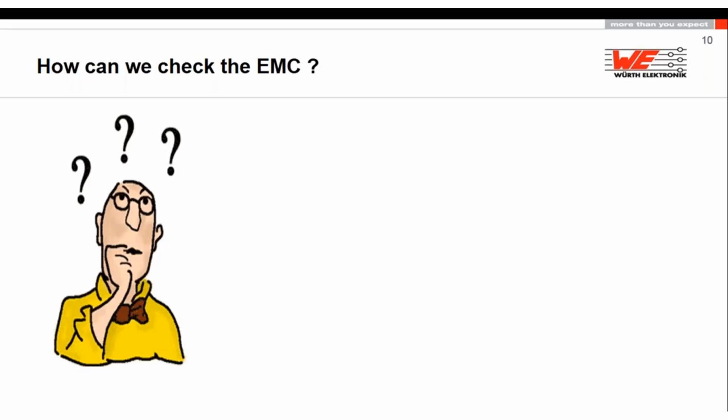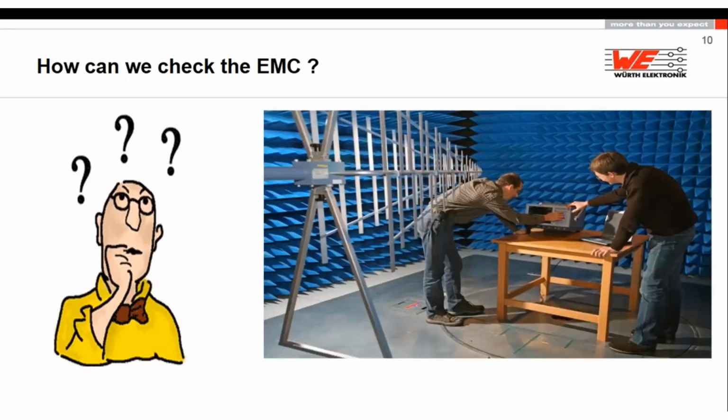If you want to hunt 1 gigahertz, you need 3 times higher bandwidth. So you will need a 3 gigahertz bandwidth as well. With a 250 megahertz scope, it will be impossible to see that. But much better is, of course, if you have money for investment and you can investigate that with a pre-compliant measurement setup, like an anechoic chamber, EMI receiver, some antennas.